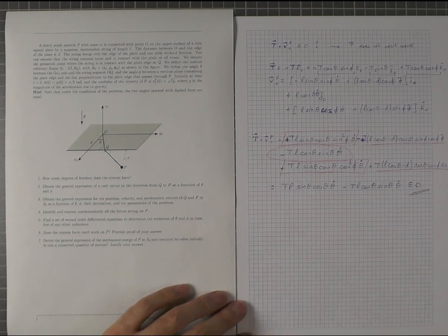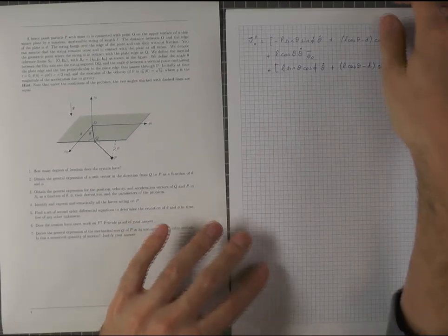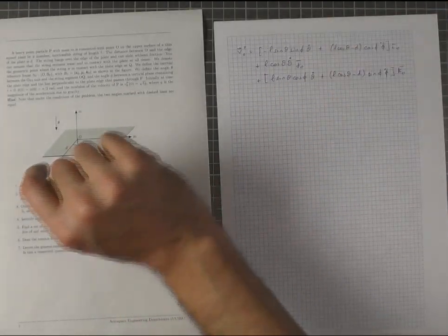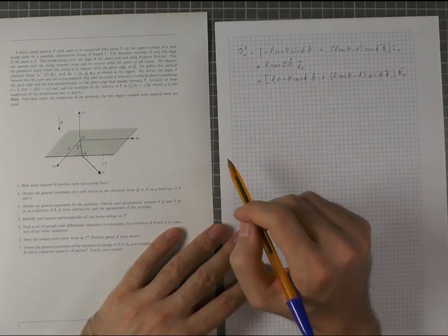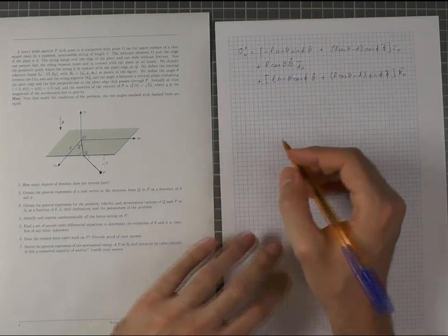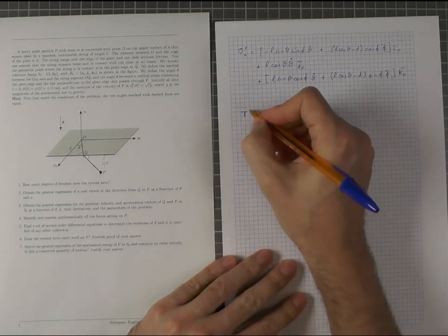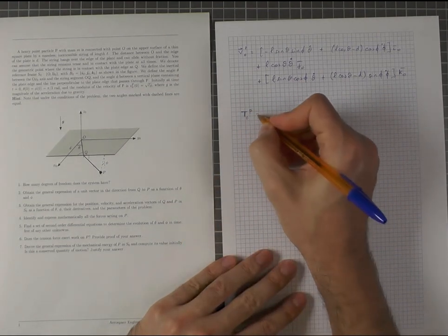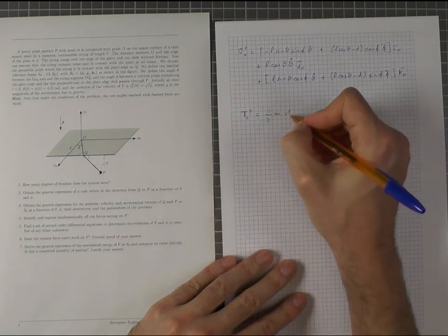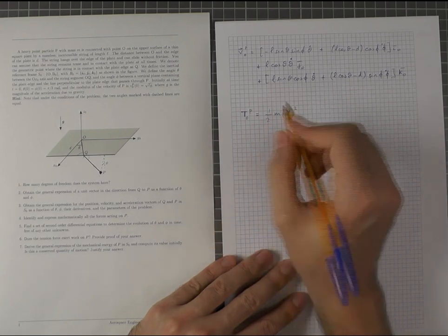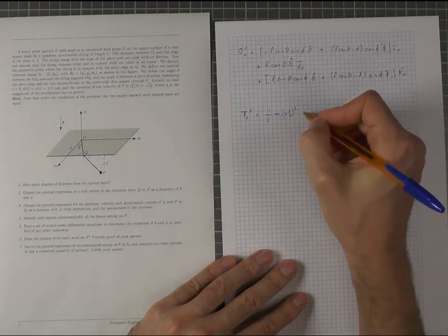Okay, so to start with that, what we want to do is to compute the kinetic energy and the potential energy of the particle. Okay, so I have started here with the expressions that we already have for the velocity. So if we want to compute the kinetic energy of the particle P in reference frame 0, we have to compute 1/2 of m v_P0 squared. In other words, we need to compute the dot product of this velocity with itself. Okay, so let's do that.